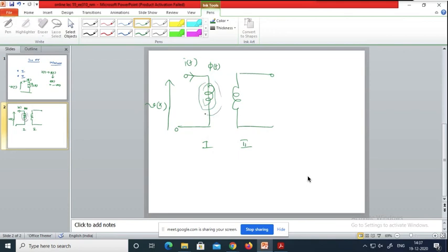This flux might also link coil number 2 due to its vicinity to the first coil. So some part of this flux is linking coil number 2. Therefore, an EMF will be induced here, because of the induction effect between coil number 1 and coil number 2.